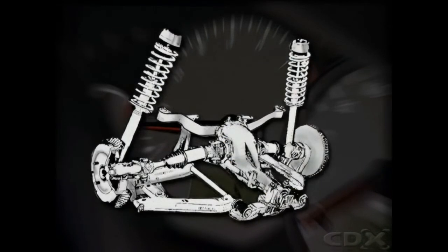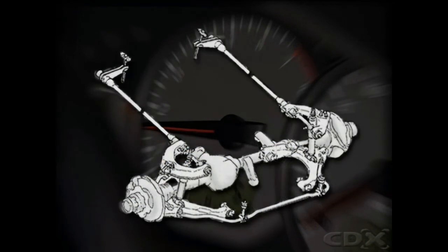This arrangement consists of coil springs and strut, splined sections, lateral wishbone and external drive shafts. This independent driven or live axle arrangement can be either front or rear suspension and consists of torsion bar, upper wishbone, lower wishbone and torsion bar adjustment.